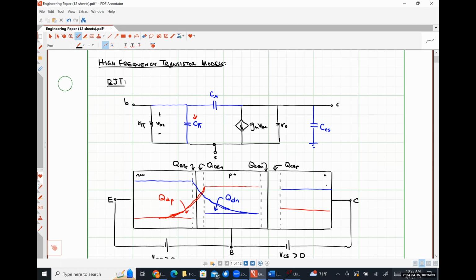But in a closed loop configuration where effectively we have feedback, even if we're intending to apply a negative feedback, at certain frequencies that will turn into positive feedback. And so we have to look at our system stability as a whole to make sure that our gain goes down to incredibly small before our negative feedback turns into positive feedback, so that we don't come up with an oscillator when we're trying to make an amplifier. So that's the context of literally everything we're doing for the rest of the quarter.